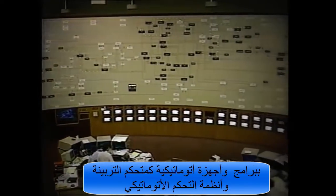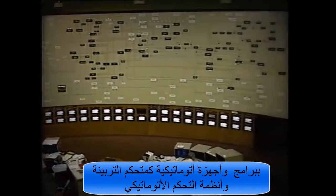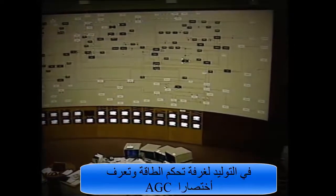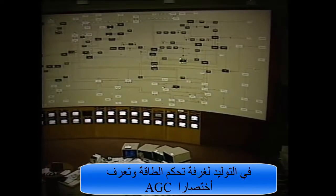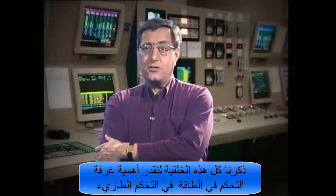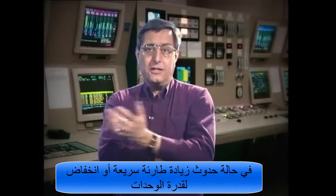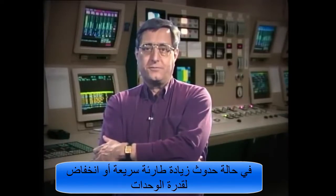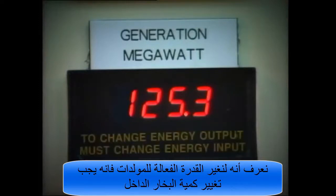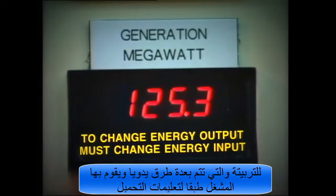However, he is assisted by computer programming and by automatic devices such as the turbine governor and the dispatcher's automatic generation control system, known as AGC. We mention all this as background so that you can appreciate the dispatcher's urgent appeal to you on occasion for either a rapid increase or decrease of unit output. We know that in order to change the generator's active power output, we must change the energy input, that is, the steam flow through the turbine.